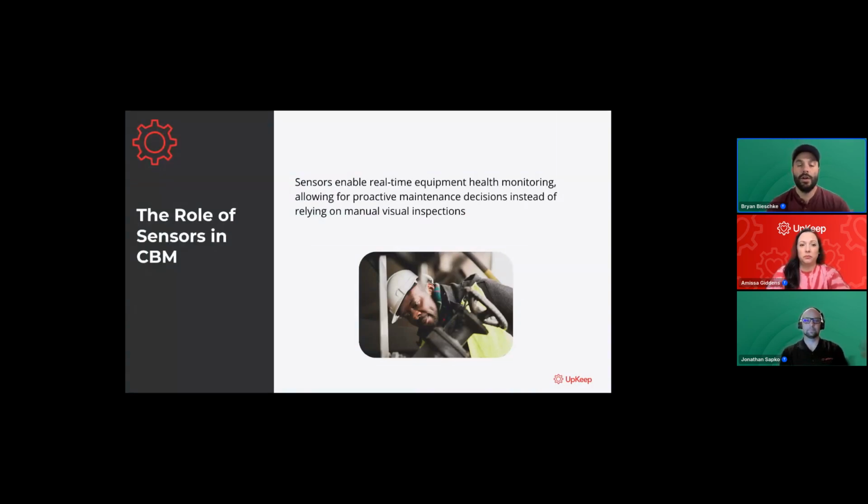So a lot of times, and I've done this, and I still think it's very valuable, to have operator-driven or technician-driven condition-based maintenance, meaning you're walking up to a machine, taking readings, taking pictures, using go/no-go gauges, using edge detection for wear and things like that. I still find it extremely valuable.